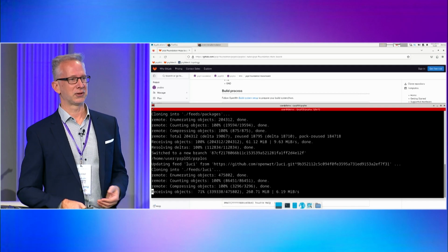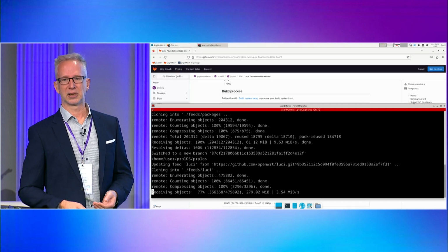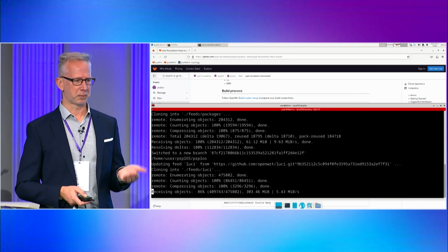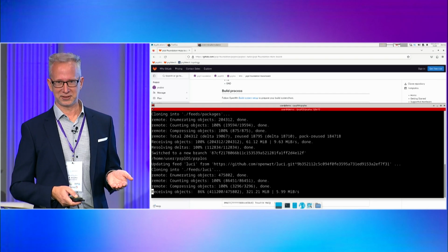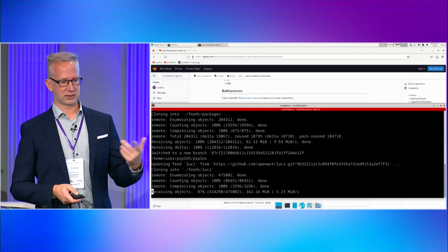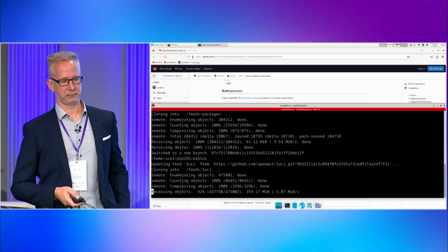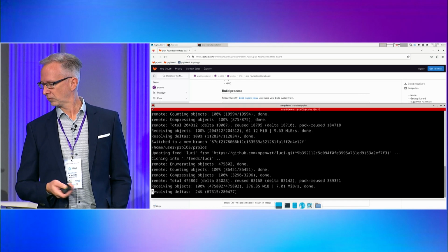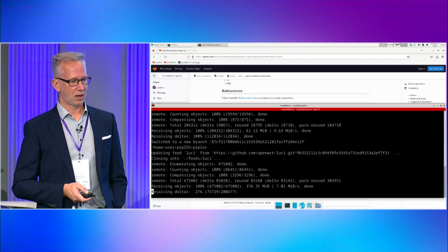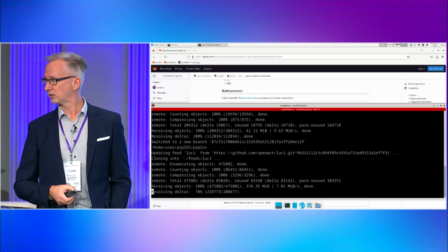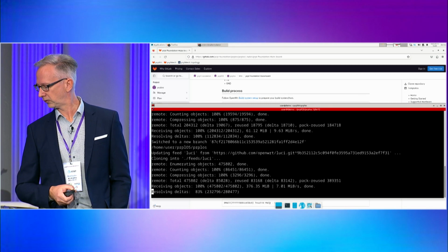After you once built the toolchain, most of the main packages, if you make smaller changes, a build takes maybe 5 to 10 minutes. That's quite fast. And after doing the build, which I'm not going to demonstrate here, that's for sure, you find the firmware files in the usual place, bin targets, and then architecture, etc. And you're good to go. Now while this configuration process is running, let's not get bothered too much with it. Hopefully it's going to be done soon.